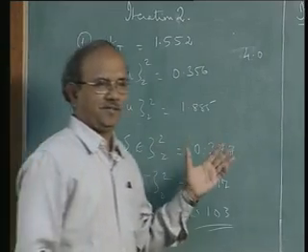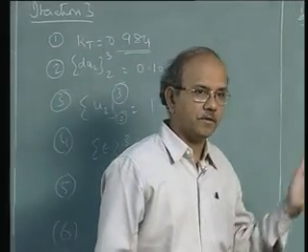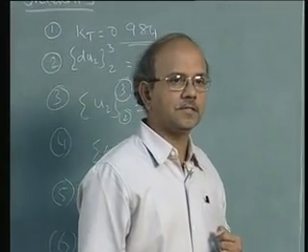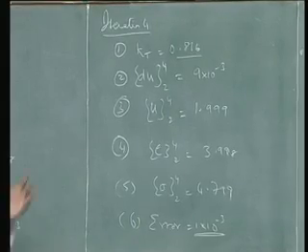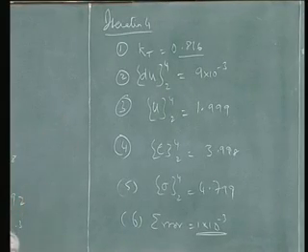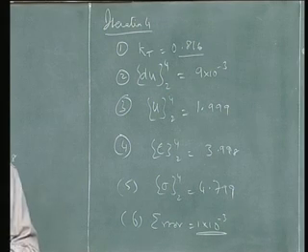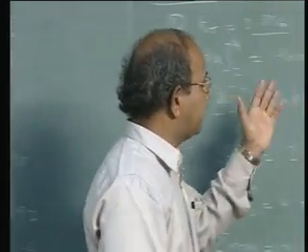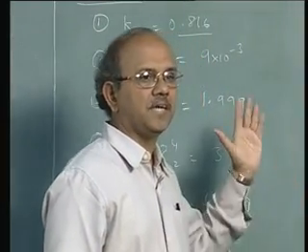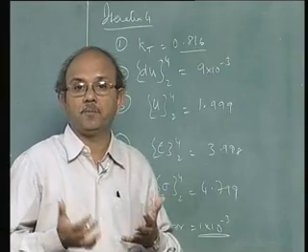This is not a very good trend, and this is what happens many times in finite element analysis when you look at these kinds of problems. At one time, this is going to be so small that convergence becomes difficult. In fact, if this happens to be a multidimensional case, K would become ill-conditioned. So you can't apply whatever step you want.